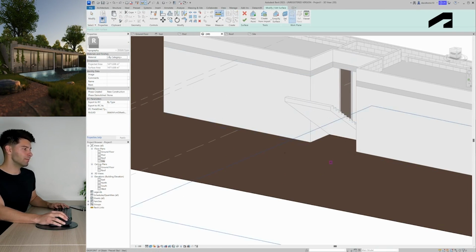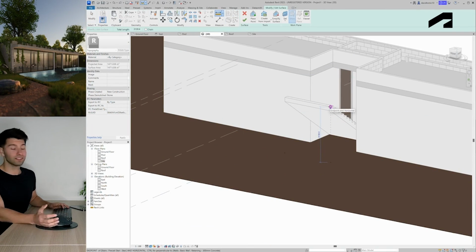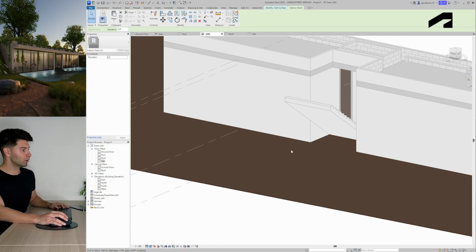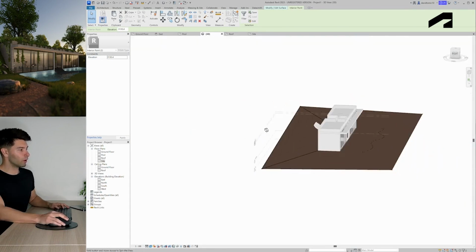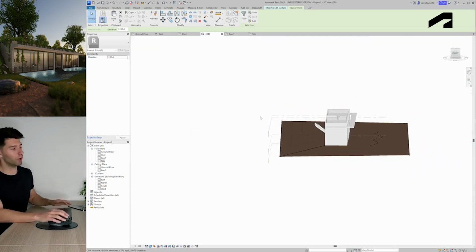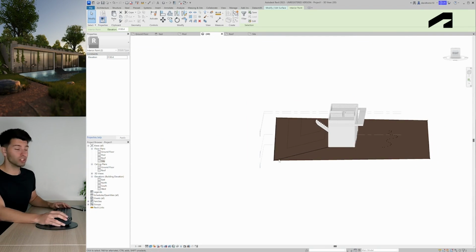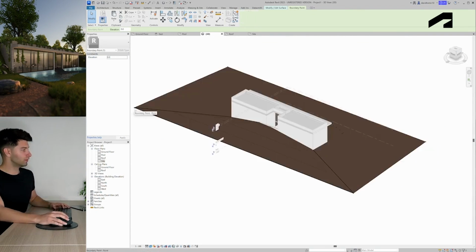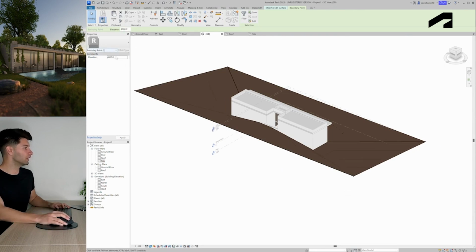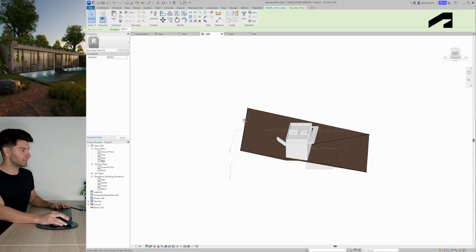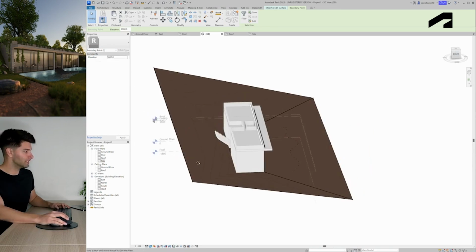So these hotspots, for example, need to be lifted to the top of this stair. I can easily measure these here, understand that's 3130.4, and highlight those 2 hotspots and adjust their elevation on the left-hand side to 3130.4. What you'll see is an automatic adjustment of our entire topography, which is an incredible feature that makes life so simple. The 2 end hotspots I want even higher to make sure that ground is falling further towards us. So let's type in 5 meters and continue to see our site fall exactly where we want it.